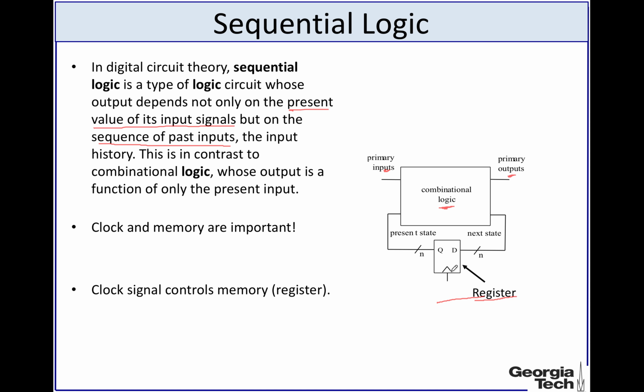So this is usually how a sequential logic block is represented. And here the important thing is that there is a clock, and this clock essentially says when the state of the sequential logic block will be updated. This clock is essentially what discretizes the time, because the state of the system will be updated at each clock pulse, or some sort of discrete time steps determined by the clock signal. So again, sequential logic creates a situation where the continuous nature of the combinational logic blocks is converted into a discrete time nature, through which the state of the system is updated in discrete time steps.